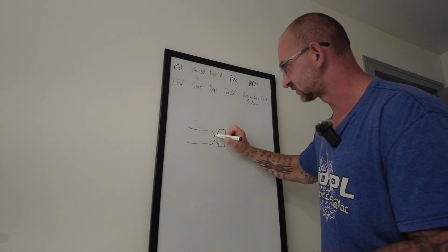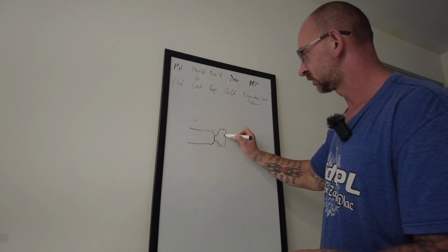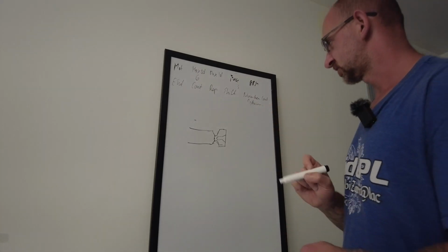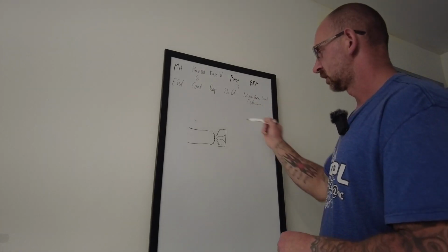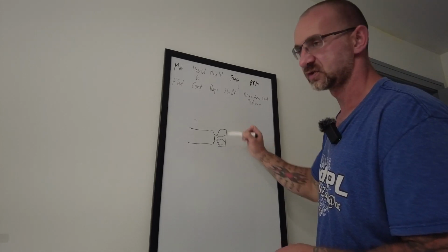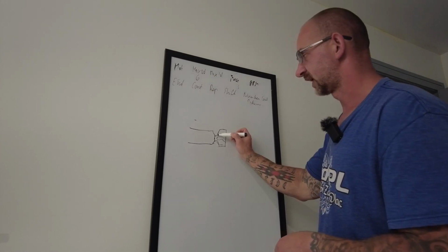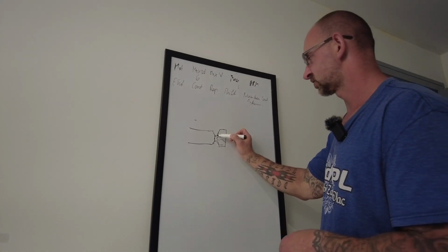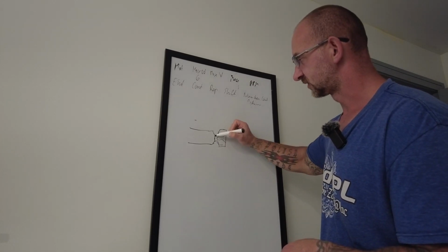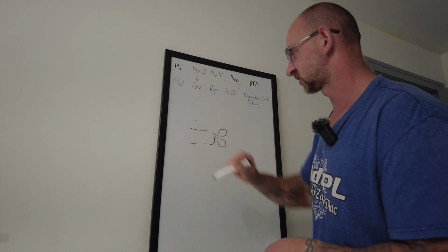And so technically this will be your 0, but you have this section where you come in and this is your center. So you tell your machine, for example, 1 inch, go here, then you can use a 35-degree tool. You can do like a -50 taper, right? It will calculate for you your finishing point Z, and then go a little bit straight, go to 0, and then throw that big chamfer over here and just continue.